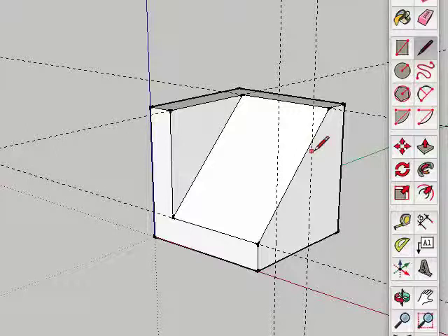So now I want a rectangle that's going to be on here. I don't know how long this line is down here, but I do know that if I start at that point, it goes back parallel to the green axis. So I can just go back and see how it's snapped onto my ruler. That's why I use rulers. Rulers can come in very handy because later on I can just erase the whole ruler. I don't have to erase parts of lines. So I've clicked on that point, come across, it's snapped onto there, click up, there. So that is my little triangle.